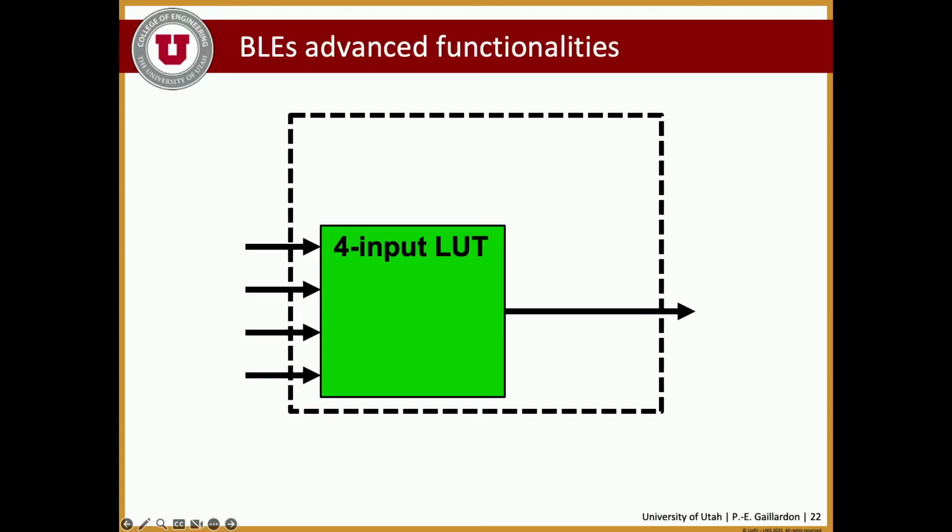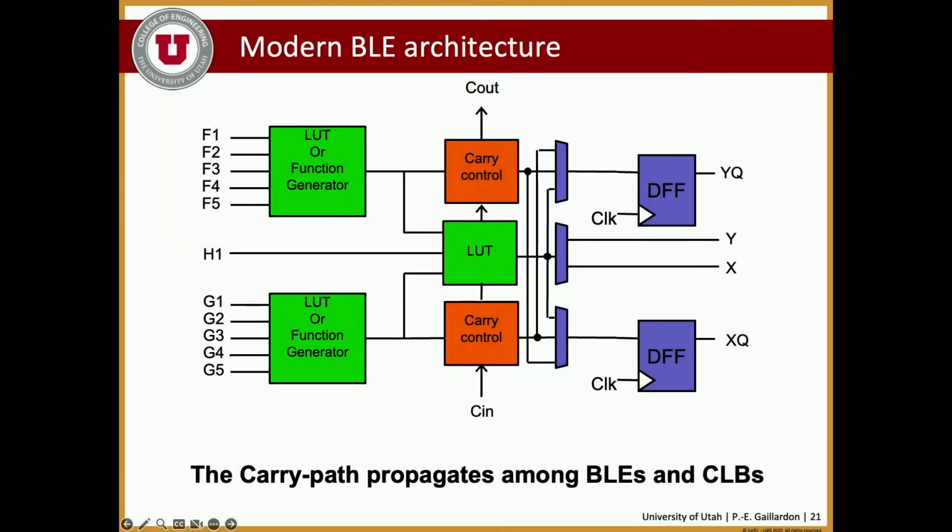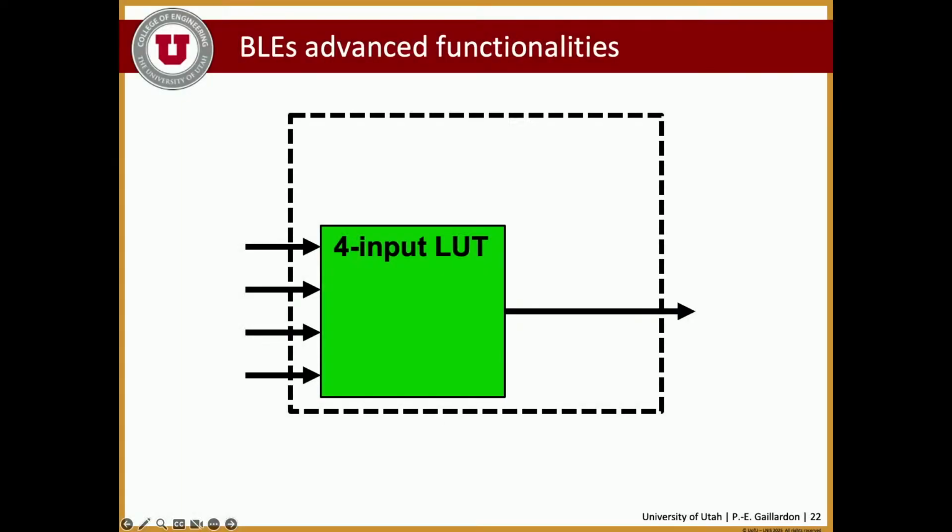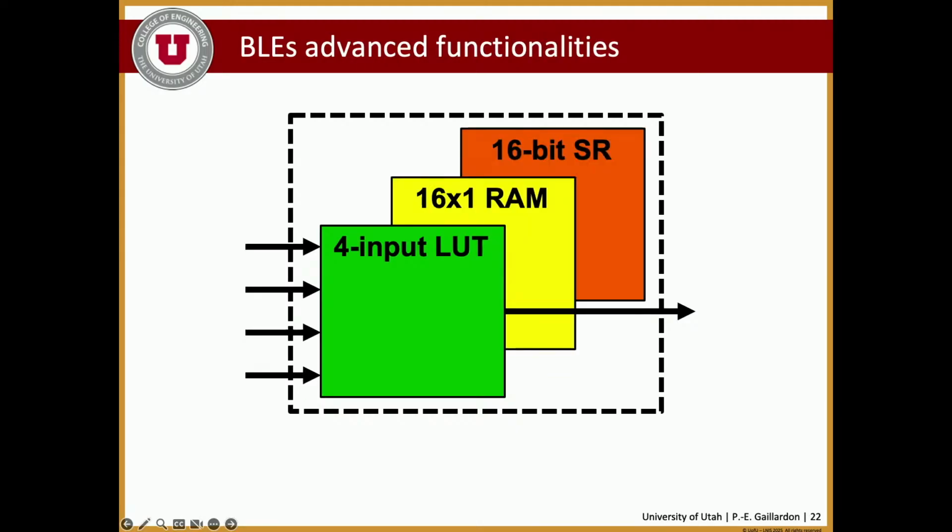And now that creates that concept of multi-mode logic blocks. These blocks are getting pretty complex, and they can implement multiple different functions, whether they are standard LUTs, whether we are using the memories as a RAM, or whether we use the registers and the flip-flops as a shift register. So these blocks can be seen through different sets of goggles, depending on what you want to implement.